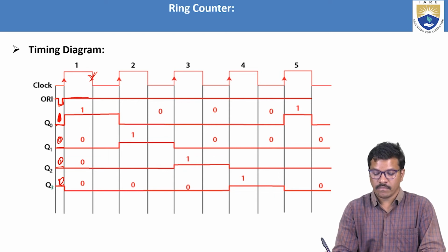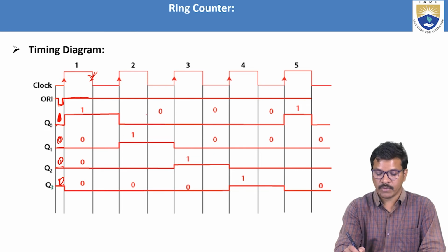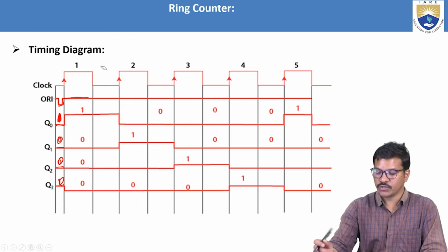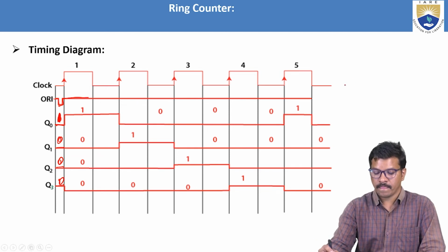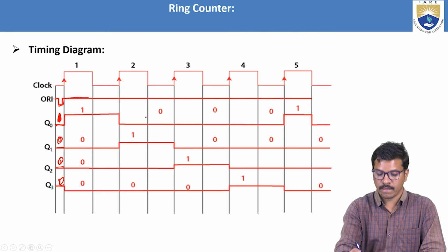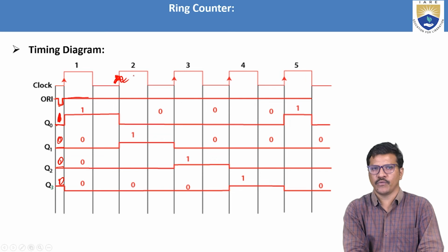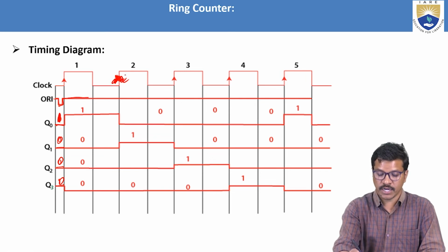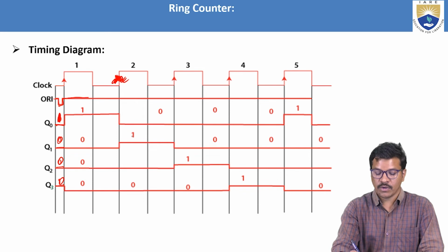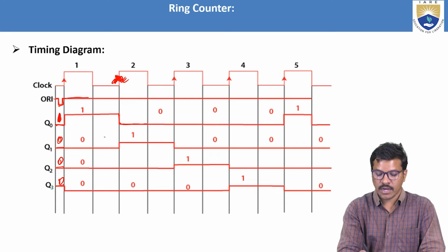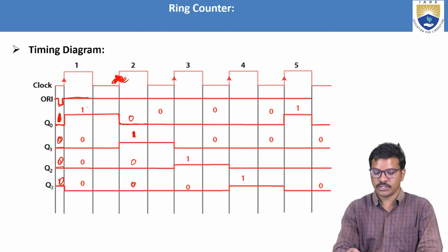In the diagram, that will become, for example, here it is positive edge clock. In the positive edge, we assume that it will be active with the positive edge clock. With this positive edge clock, that 1 0 0 shifted like this: this one is 0, this one is passed to the next clock Q1, remaining are at zeros. So 0 1 0 0.